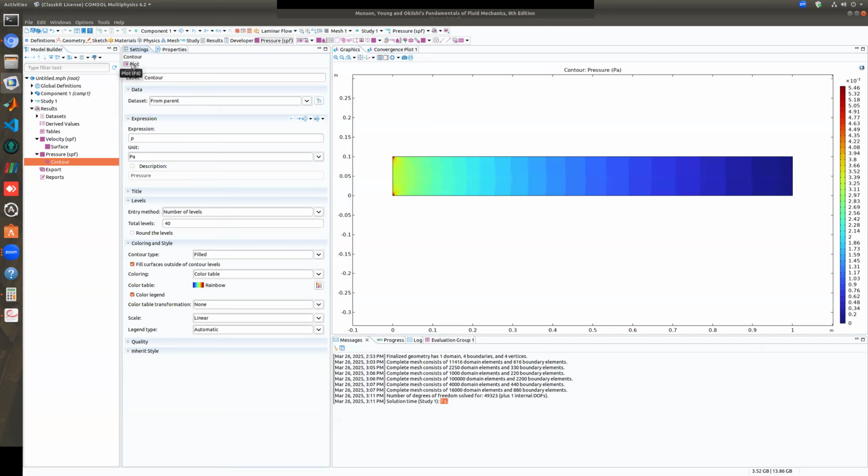So this is the pressure contour, and it is kind of very simple. In the initial fully developing part, the entrance part, there is a nonlinear pressure drop. That's what we expect due to entrance effects. And then after a certain point, if fully developed flow is reached, after that, there is a linear pressure drop, right?